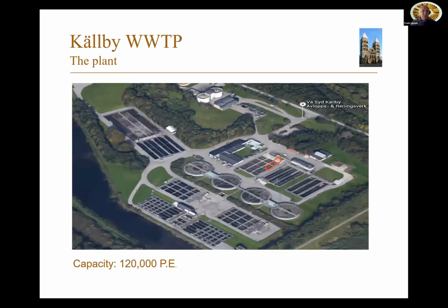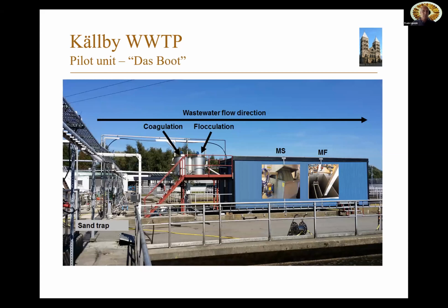That's the Källby wastewater treatment plant. It is designed for 12,000 person equivalents and is the main wastewater treatment plant here in the city of Lund. We installed the pilot where you can see the red rectangle, so it was directly integrated into the wastewater treatment plant. This is the pilot. What you can see here is the container, located after the sand trap of the wastewater treatment plant. Then we had a coagulation and flocculation step,